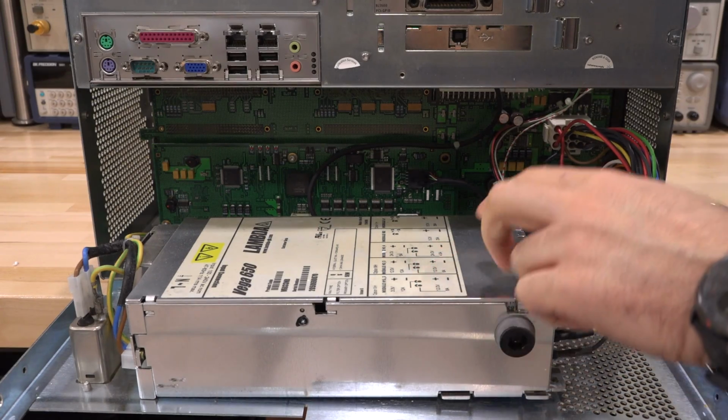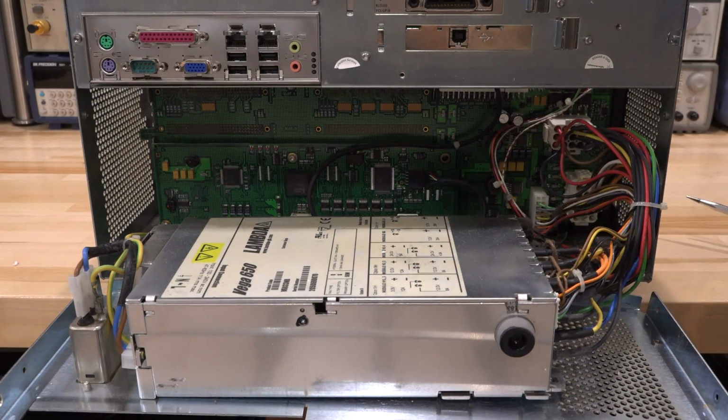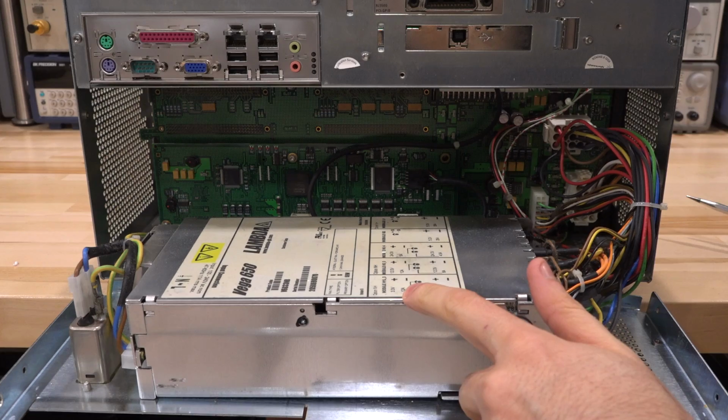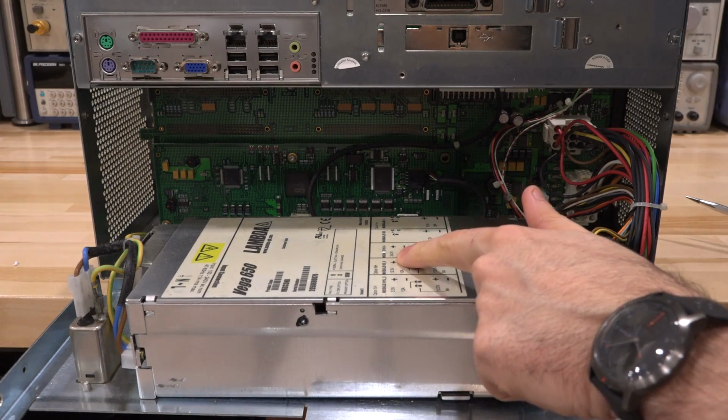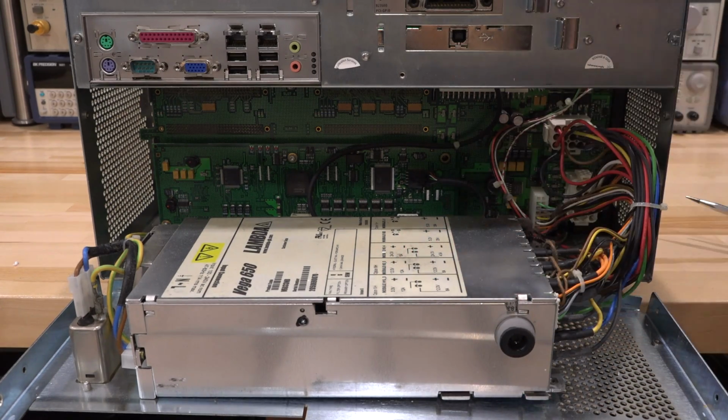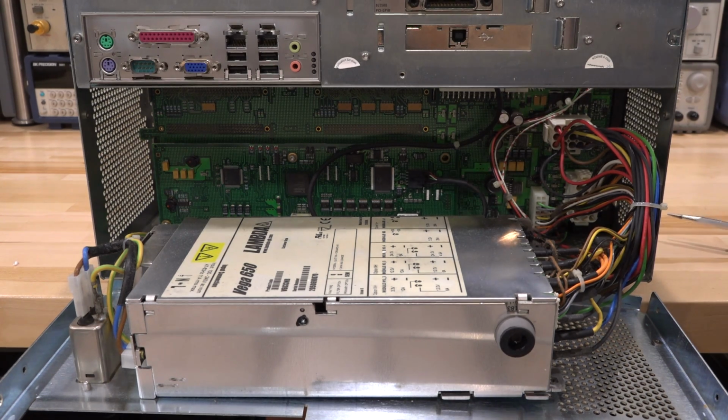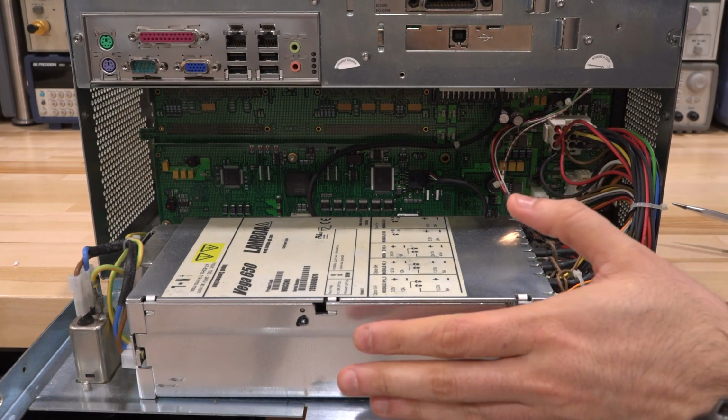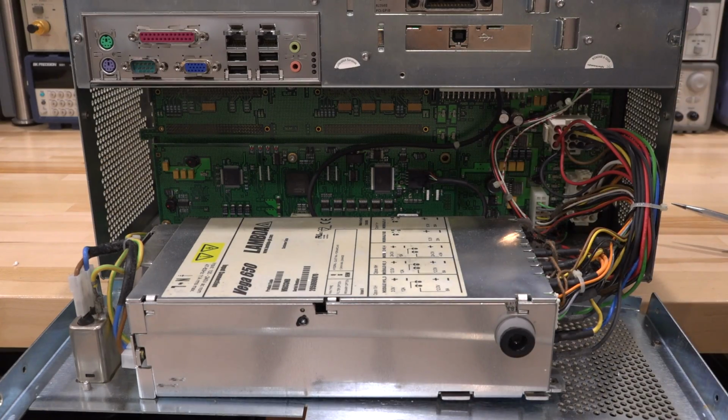This power supply has 5 modules in it: 3.3 volts, 12 volts, 12 volts, 24 volts, and 5.2 volts, and 5 volts for different logics and buses and power supplies, drivers, and so on and on. This thing definitely has silicon and non-silicon parts in it. Few connectors connect the power supply to the chassis, so it's actually quite serviceable. It's obviously intended that the Lambda power supply can be removed.